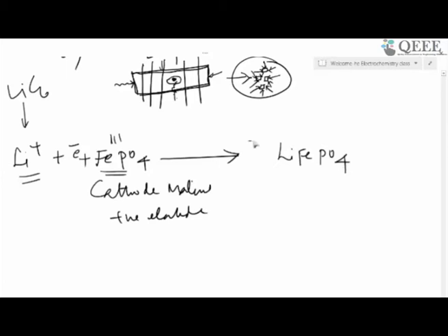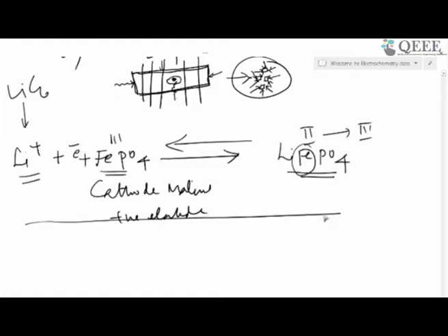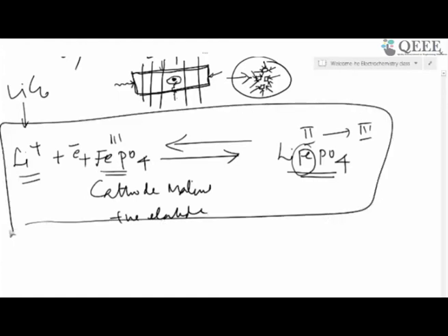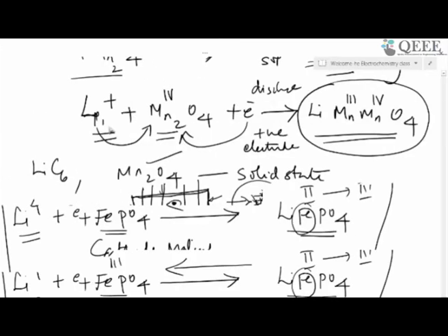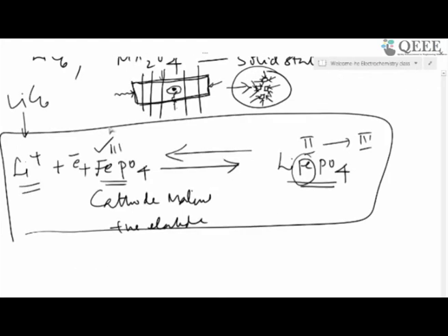So when you charge, the lithium from this matrix will be stripped. As it is stripped, one iron also will be oxidized from the oxidation state of 2 to 3, and then it will come to your graphite electrode where lithium will be intercalated again. So this will be the charge-discharge reactions of lithium iron phosphate cathode materials. Why the iron metal is interesting compared to the manganese, or there is one more metal called lithium cobalt oxide.